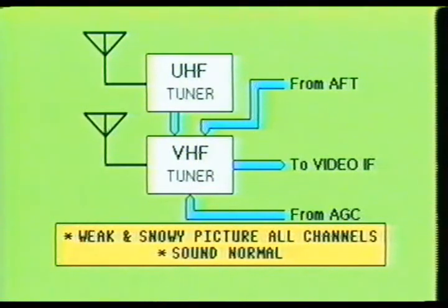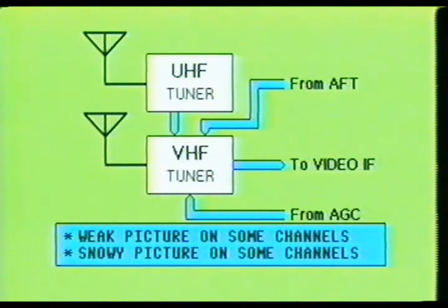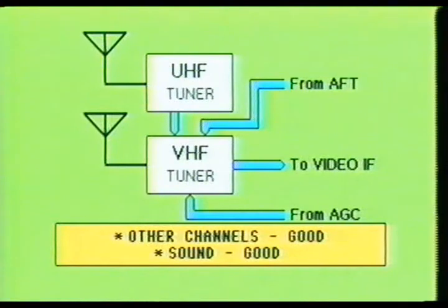Defects in the tuner stages will also cause the picture to become weak or snowy on all the channels, and yet the sound will be normal. The picture could also be weak or snowy on just a portion of the channels, while the rest of the channels are normal.